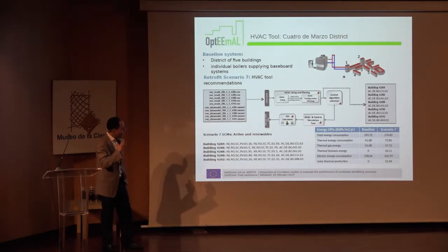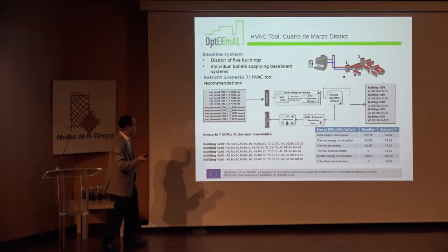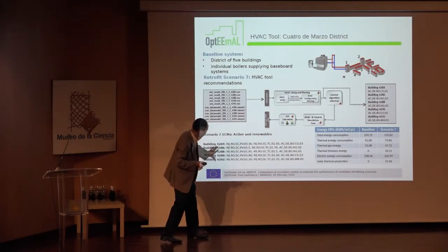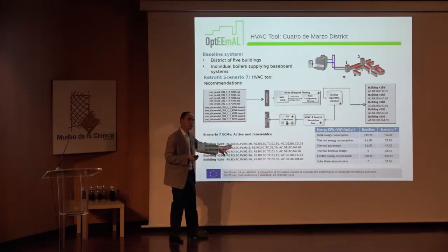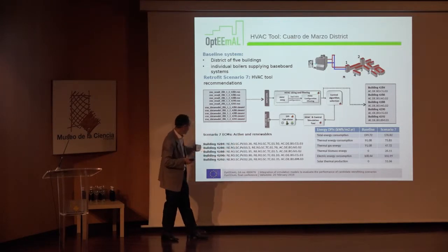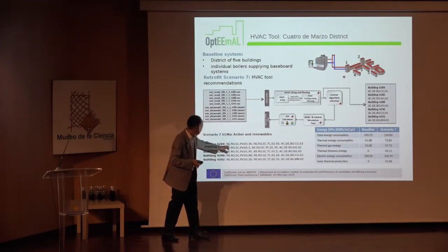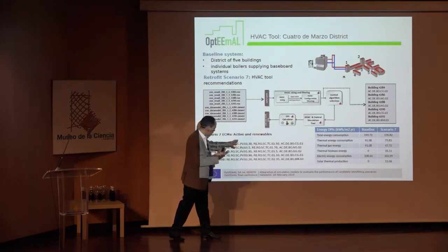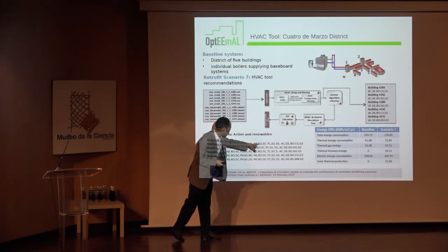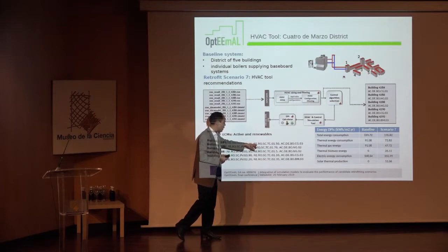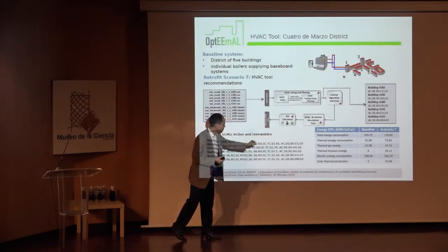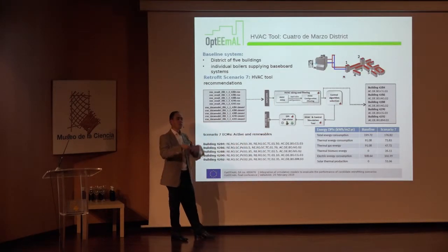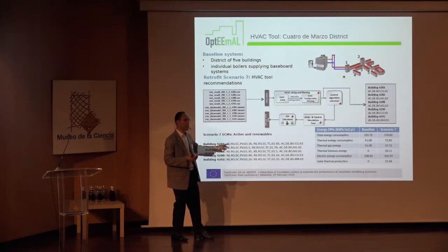And the platform or the optimizer is also requesting that we implement renewables. So this is the full active control and renewable scenario per building. There are also passive elements that are not included here. So we have renewables, we have PV for this building of this size, and also a thermal collector of that size, and also that boiler. So this will be the system that will be implemented in this first building, and so on.